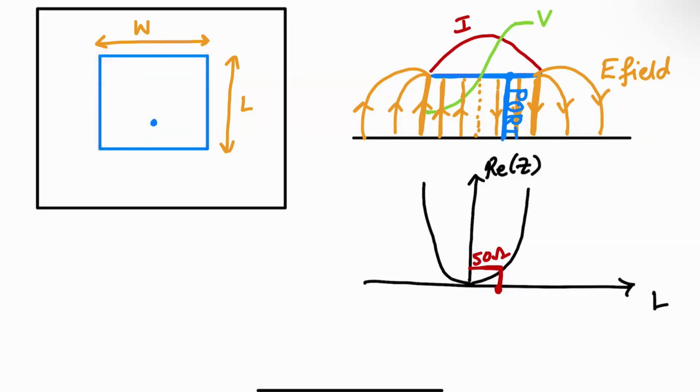And that's because the H field kind of goes around just like this. Right, so you have some edge current on the top surface, but there's almost no current in the middle. Whereas on the bottom surface, you'll have pretty strong current everywhere. Yeah, and of course, the current decays on this edge and this edge. Okay, so these currents don't really radiate because they kind of cancel each other out, similar to a transmission line. But it is really the current that's on the ground plane that's out here that radiates.